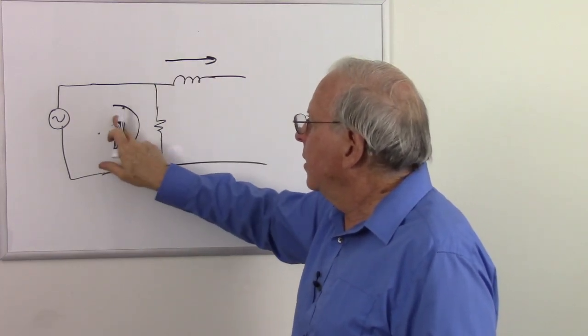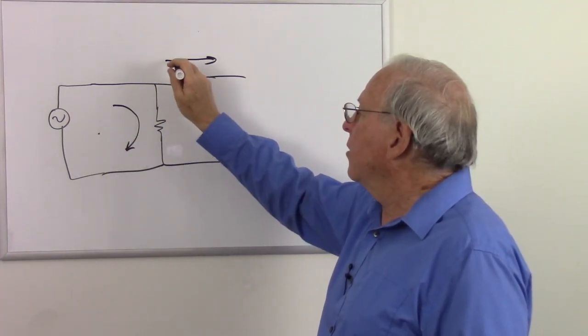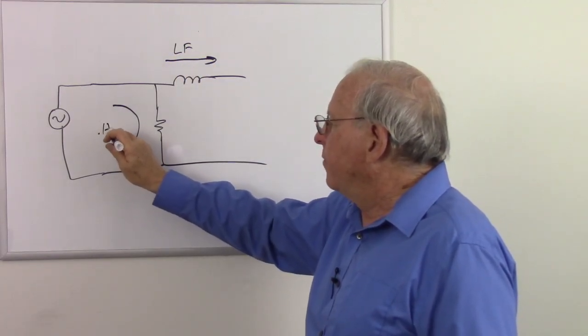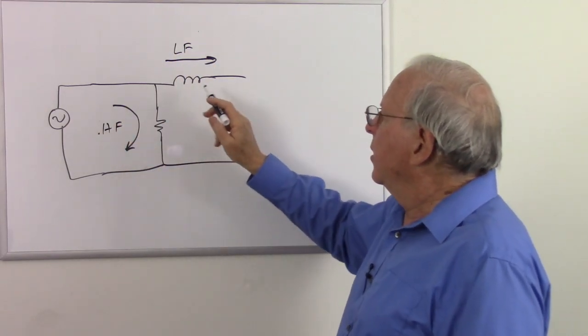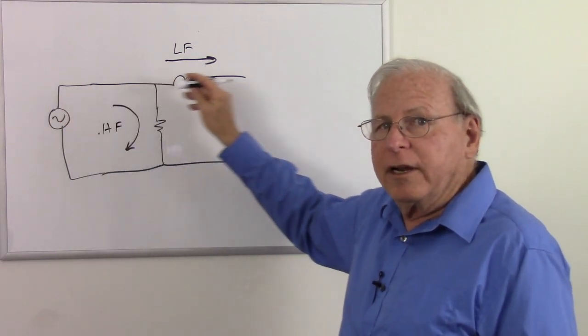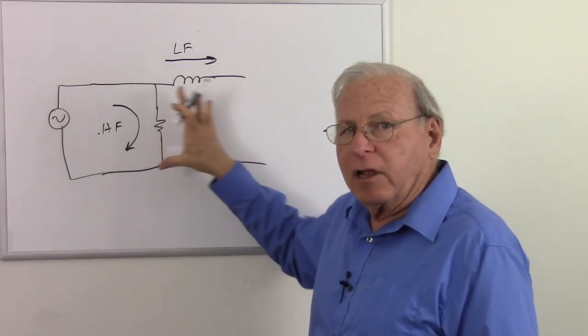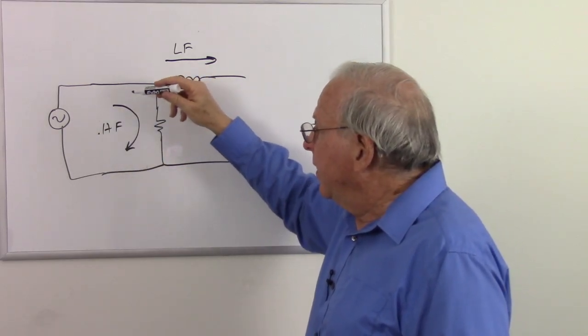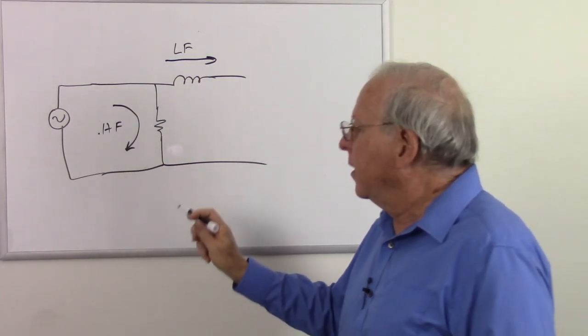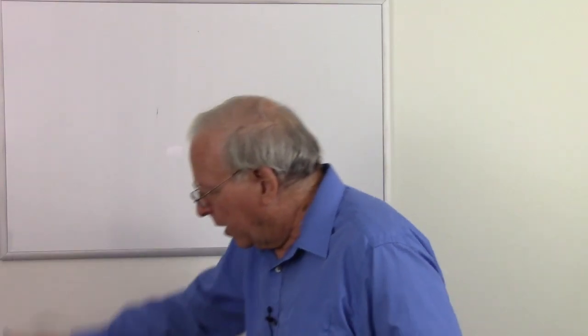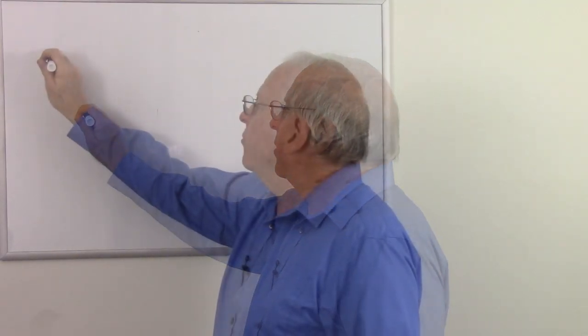And if we swap these around, now high frequencies are blocked, so low frequencies go through the inductor. High frequencies, therefore, are shunted away. So if our signal goes through the inductor, it's a low-pass filter. If the signal goes parallel to the inductor or shunted by the inductor, that makes it a high-pass filter. So let me just draw both so we can compare them and see how they are in our minds. So here's circuit number 1.